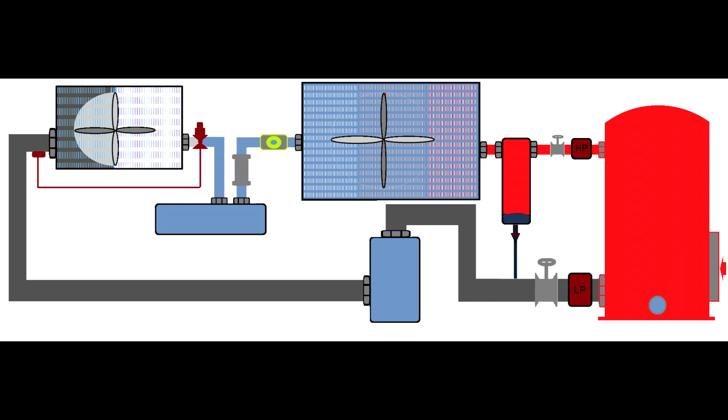Sometimes it can go into negative pressure, and that will make the compressor suck the oil from the crankcase and push the oil into the installation. The compressor will get red hot, and with the high temperature the compressor will prematurely die. So make sure you're not undercharged.